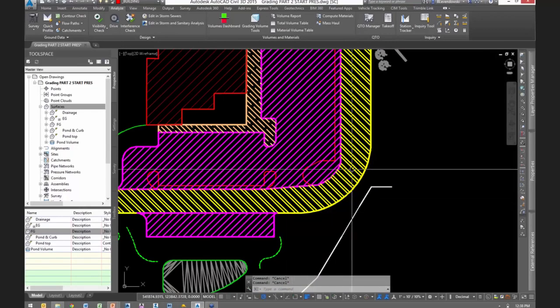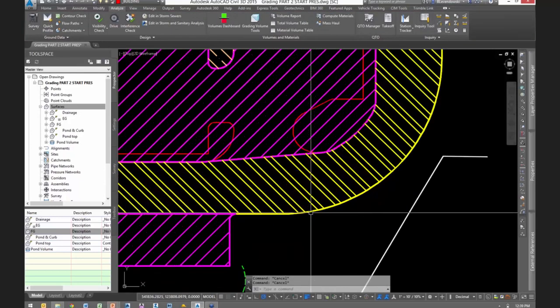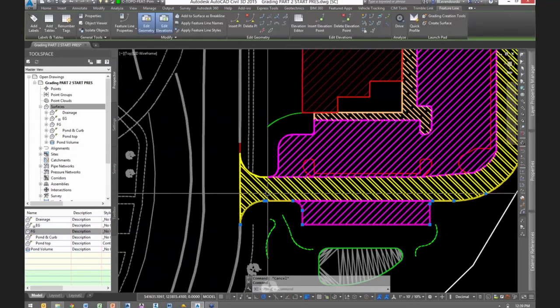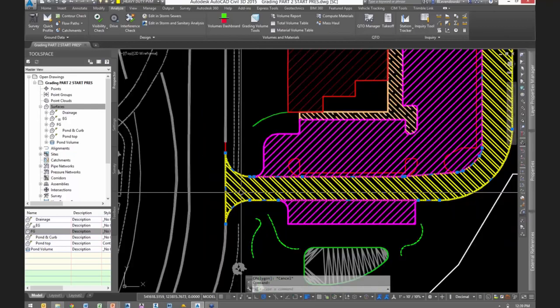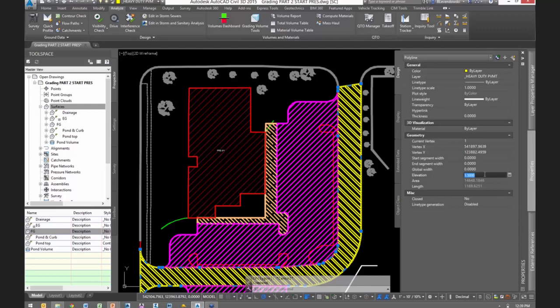This is heavy duty, okay? I have a 1.5 foot subgrade cut in this area. So from finished grade to bottom of subcut is 1.5 feet. In the magenta area, I have 1 foot. In this sidewalk area, I have 8 inches. What I've done is I've set these polylines for those areas. This one right here, I have a yellow polyline. That's my hatch boundary. I've set the elevation of this to be 1.5.